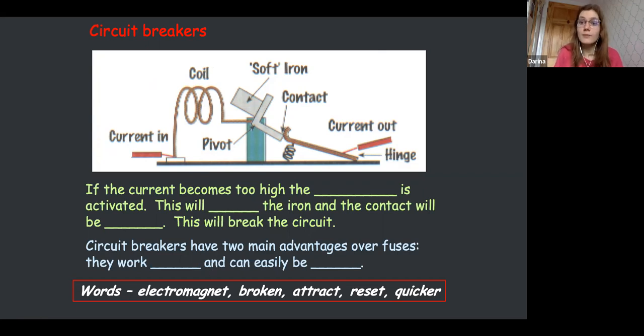If you went lower than your operational current, your fuse would just blow even when your circuit was working normally. If you go much higher than your operational current, then the fuse might not work, or it might work a lot more slowly when there is a short circuit, and that's dangerous. All right, fab. So that's two safety mechanisms, as well as the earth wire that we use to protect ourselves from electric shocks and stuff like that.